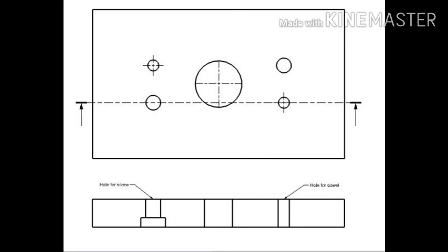Third is the contour of the opening should be made as simple as possible from the machining and finishing point of view. The bottom plate is of good quality mild steel and the thickness should be strong enough. The calculation we'll see in my next video.